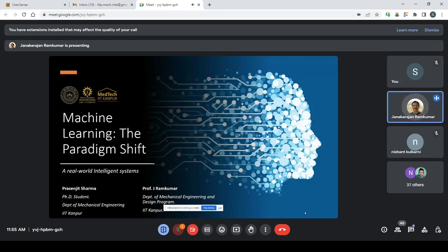In metal cutting, the speeds will be phenomenally high. In metal forming, the speeds will be very low. In metal cutting, the pressure per unit area is very large as compared to metal forming. So if you understand exactly the material property, and also know the process and its parameters and their influence, then you can start dictating the output. For example, the first part itself can be the best part which can be put into reality.